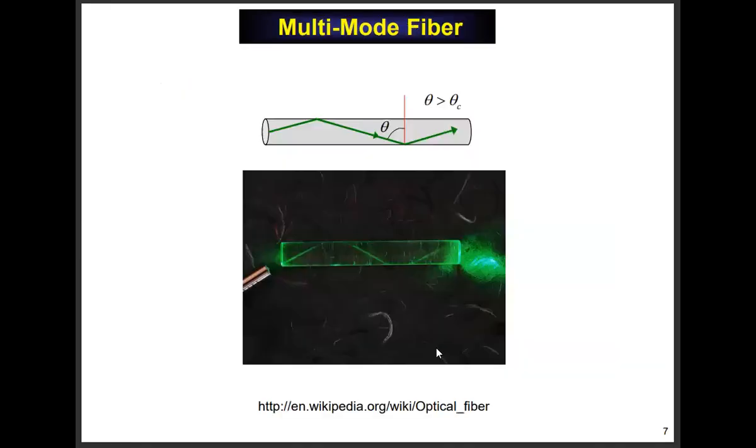Okay, now because we talked about the critical angle effect, let's go ahead in a little bit more detail, because I think you can understand everything about it now. Here's a picture from a Wikipedia page. So basically, think of a beam of light. Now remember, all our theory, like I mentioned, is based on plane waves, not narrow beams. But again, this is optical frequency. So even though this narrow beam, which is 1 millimeter wide, might still be 1,000 wavelengths, right? So the plane wave reflection theory still works pretty darn good, actually.